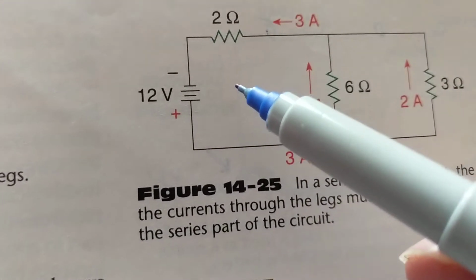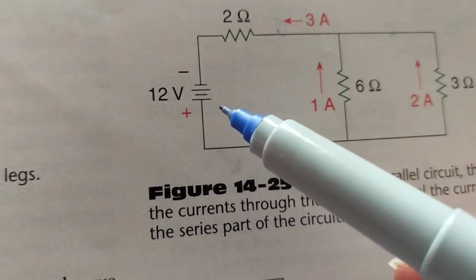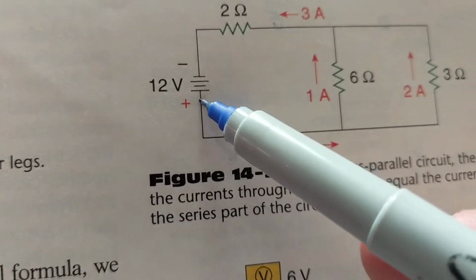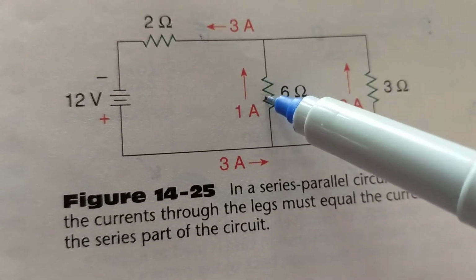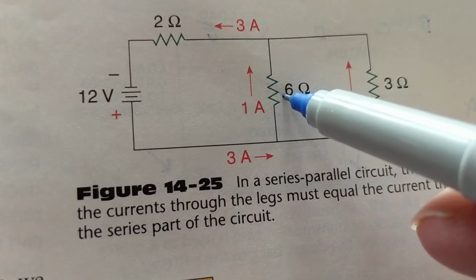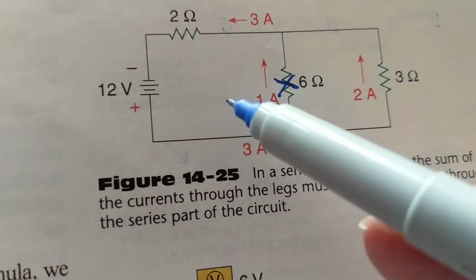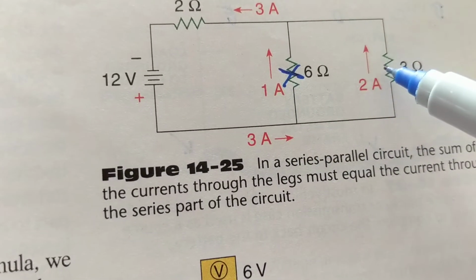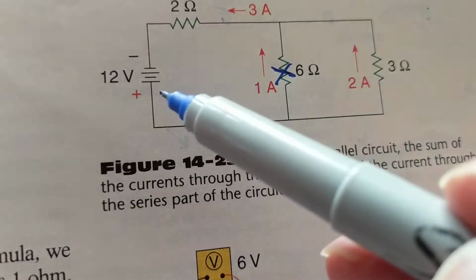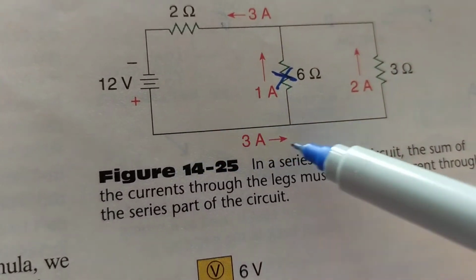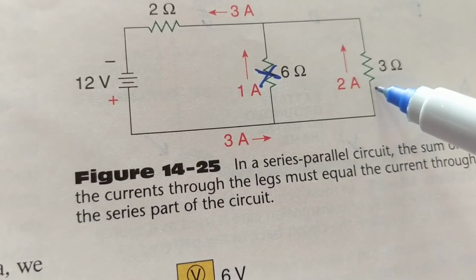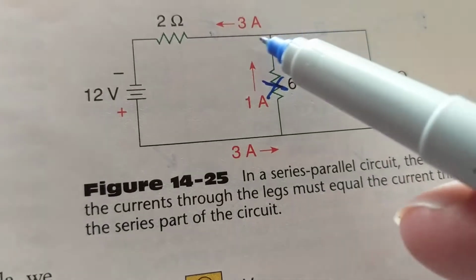So now let's go over here. This parallel circuit over here. Let's say this opens. This is tricky. Let's say we'll take this one out of the picture. Does current still flow? Let's say this is a bulb, there's a bulb, there's a bulb. Does current still flow? Current can still flow. Go here, here, here. Through this one.